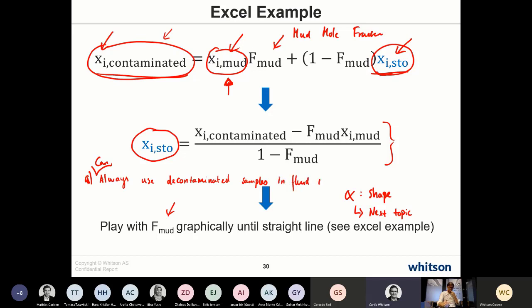What we prefer is, if you have a large set of data from production samples and PVT data, we'd rather build the equation of state with those data. You can do a PVT match of all data with an EOS that includes oil-based mud components, which is another way to do it. But so you can do it, and you should never throw away data.